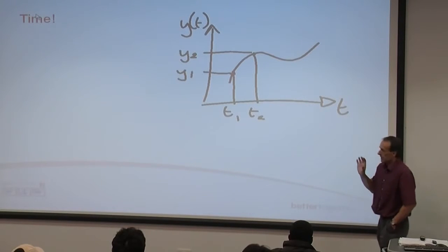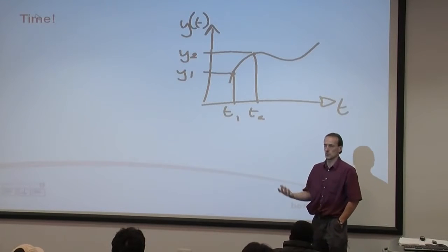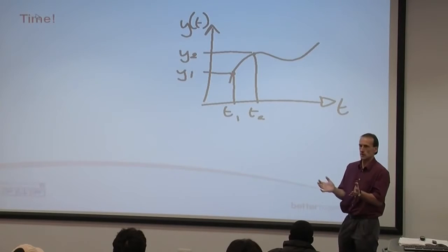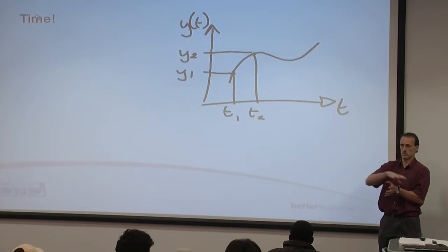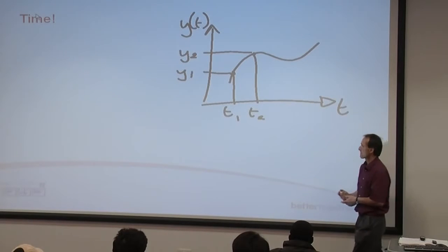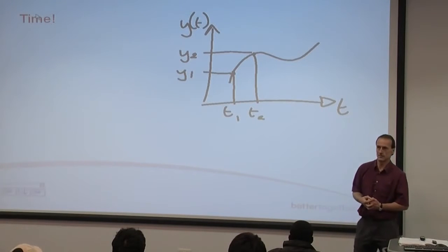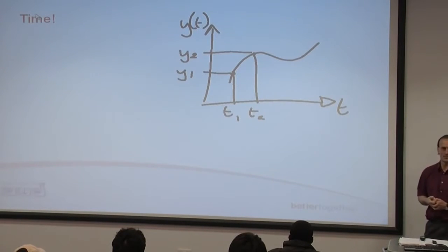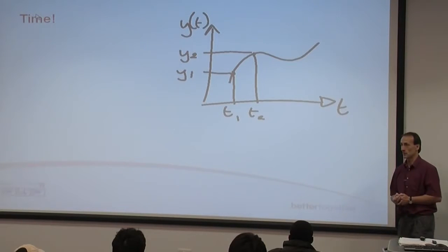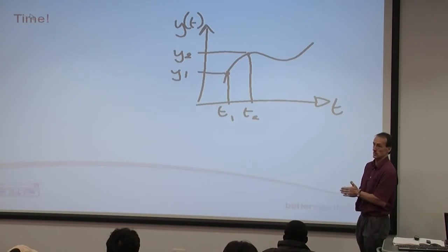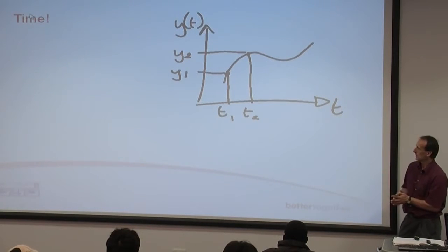If you're measuring a variable like this with a digital computer, connecting up some kind of interface card to the real world with your PC, how close together can you get T1 and T2? Depends how much money you've got, basically. It depends on the speed of the I/O card and the speed of the computer, and a lot of that is down to how much money you pay.